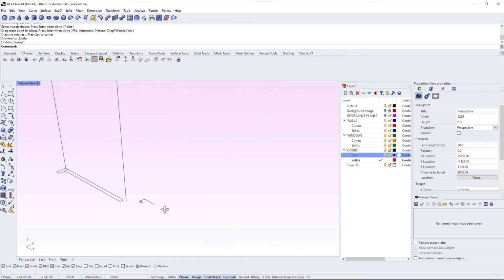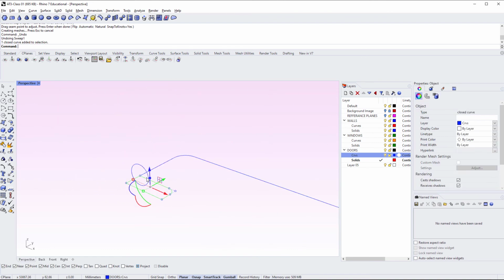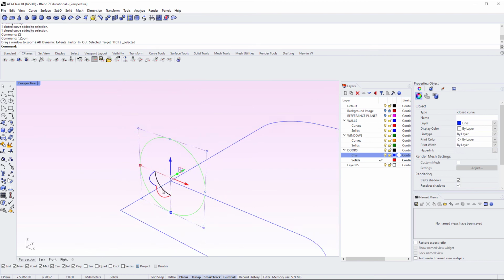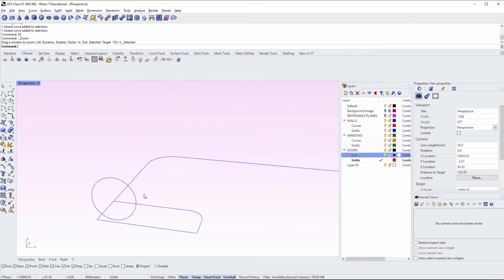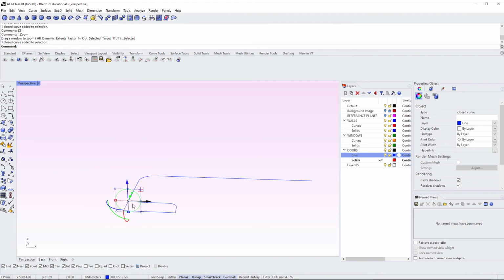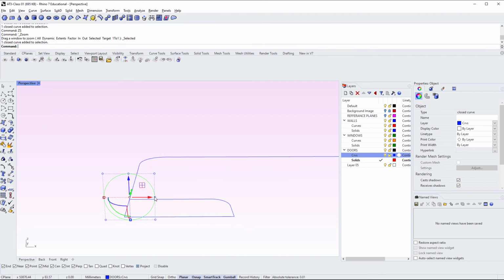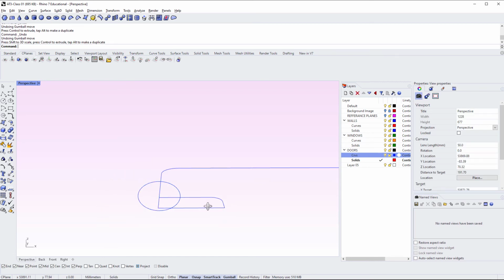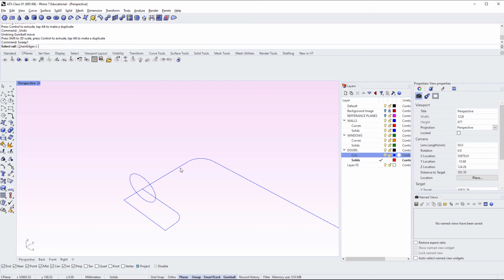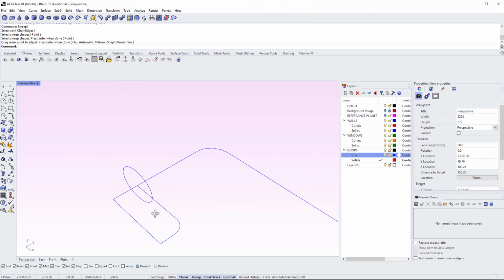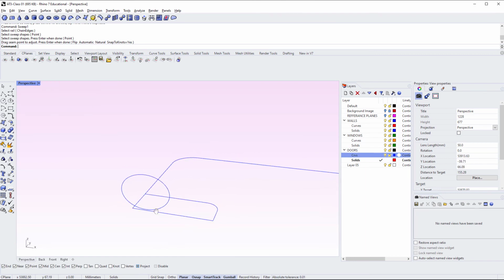If you want to change the door handle profile, you can do that too. So in this scenario here, I'm using what's known as a lever door handle. But if you wanted to change this shape into another shape, you could do that. If you want it to be an ellipse shape, which would be rare, but if you did, you could do that and then use the sweep tool. So again, sweep 1, rail, profile, enter, enter. Okay, that could be a rectangle, it could be a square, it could be whatever you want.